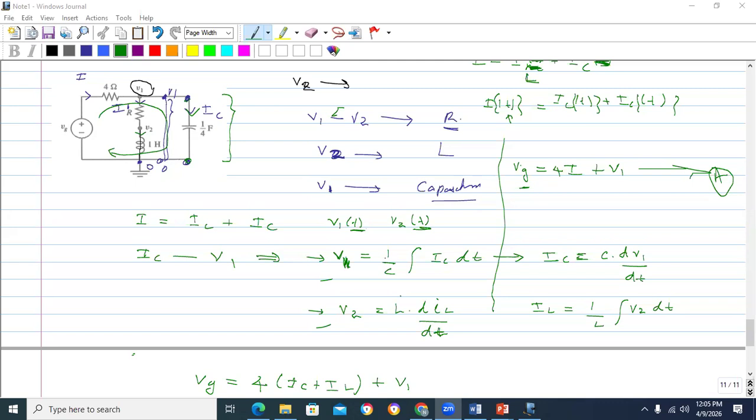So in this equation, it is plus. And the inductor current is also going into the inductor. So in this equation, it should be plus, it should not be minus. But when you apply Kirchhoff law, sometimes it can be minus. For example, if you apply the Kirchhoff law in this direction, this IC will be a minus value.